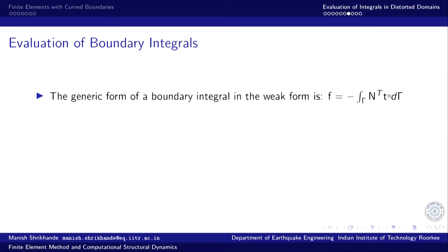So, that leaves us with the only remaining term in the weak form of the weighted residual statement, that is the boundary term, evaluation of the boundary term. Boundary term is evaluated in terms of these surface tractions, and T is this vector of surface tractions on the boundaries,